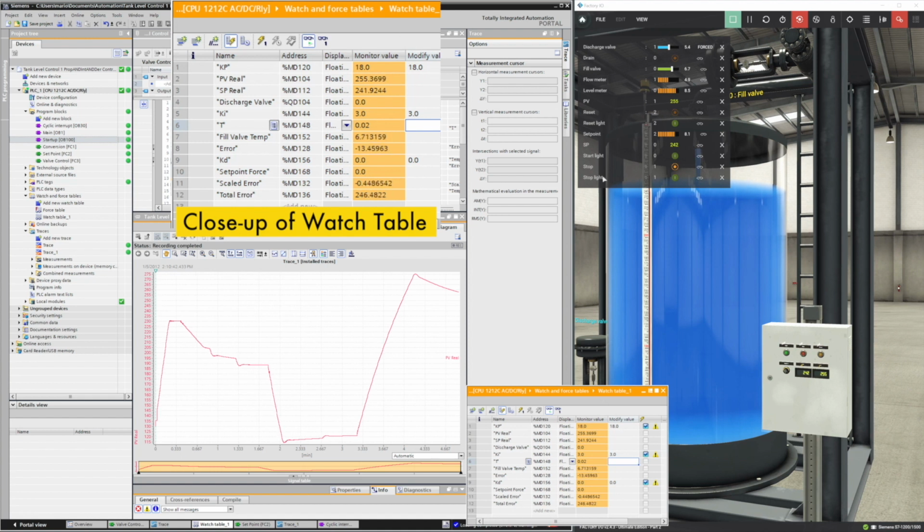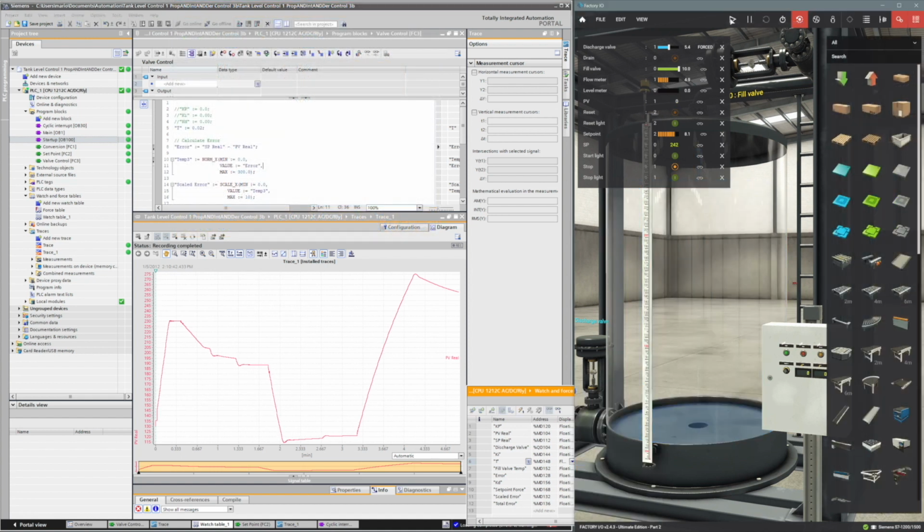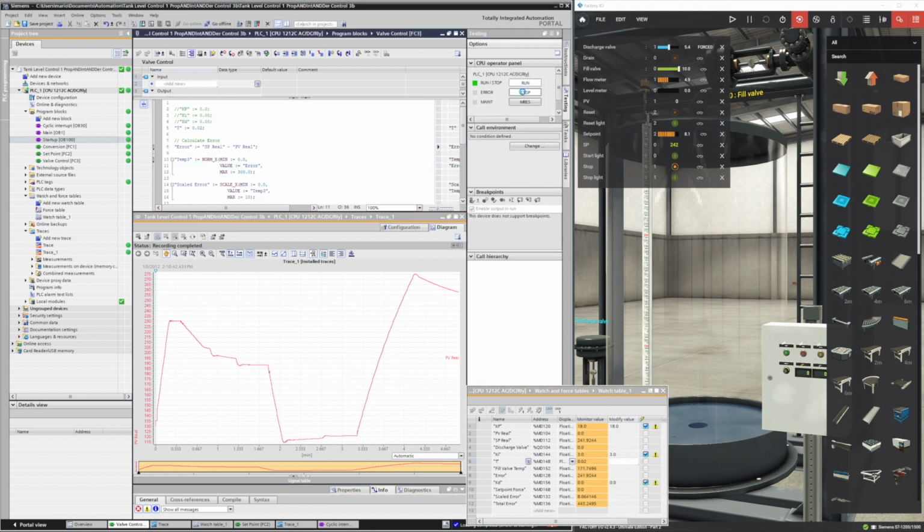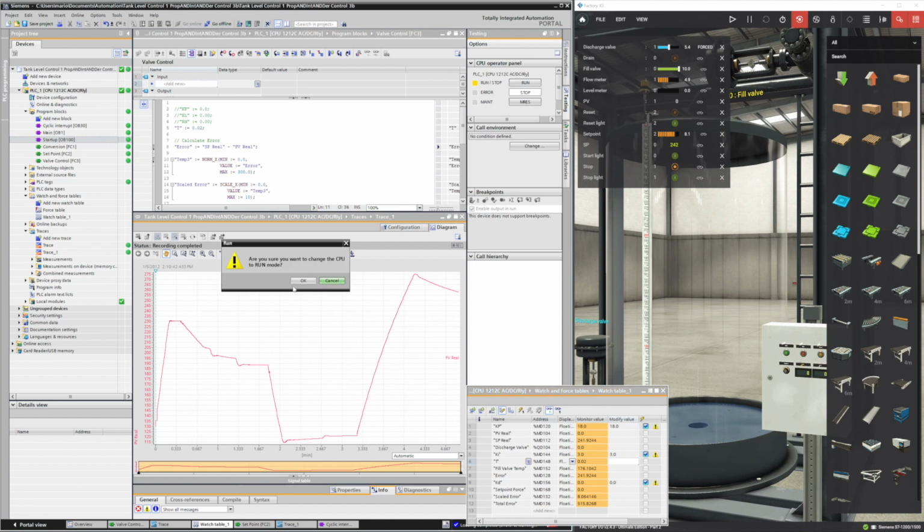Ah, it's going again. Right, let's stop FactoryIO and the PLC and now add in a derivative. Normally a small amount of derivative would dampen the overshoot, but in the case of a water tank setup like this one, we will see that it has a limited effect and in some circumstances can make the system unstable. In my opinion, as we will see, I don't believe the derivative is necessary with this particular water tank setup, but I thought I would include it for completeness.